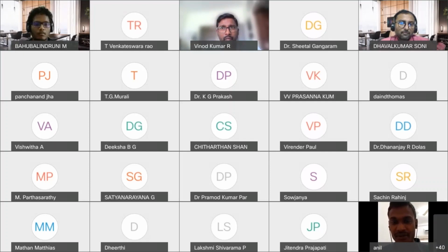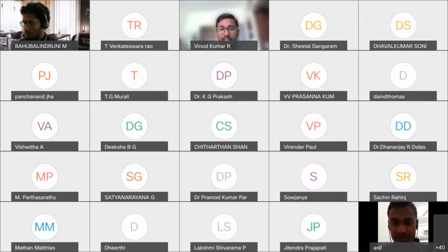Actually, when we talk about simulation software for robots, we don't have this option. But as you mentioned, for a collaborative robot we need to fix different values for the force coming onto the robot. This can be manipulated using additional software in the cobot. When we go with the cobot in the real-time controller, there is additional software where you can fix the sensitivity, or change the torque sensors of each and every axis, the minimum and maximum tolerance limits. So whatever testing you require, we can do it over there.